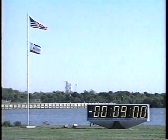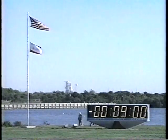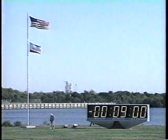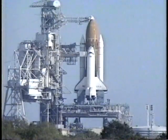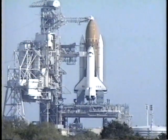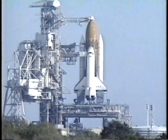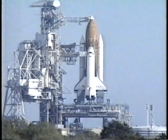NTD, this is Stage Ready. Go ahead. Yeah, we have water spray boiler number 2, steam vent temperature trending down, and this is typical and expected. We're 1 degree away from losing the water spray boiler OK, which feeds into the APU, ready to start talkback. And we're to tell the PLT that if he doesn't have a gray talkback at APU pre-start, that he's to ignore that and go for a nominal APU start. Okay, copy. And this is already published. Yeah, this is covered under hydraulics SSID number 10 LCC.